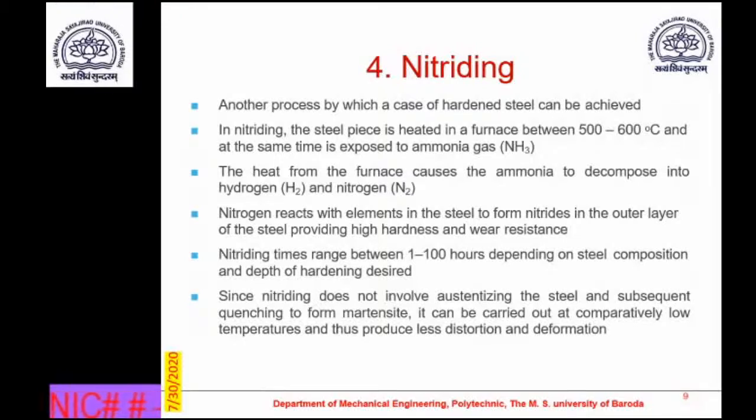Since nitriding does not involve austenitizing the steel and subsequent quenching to form martensite, it can be carried out at comparatively low temperatures and thus produce less distortion and deformation.